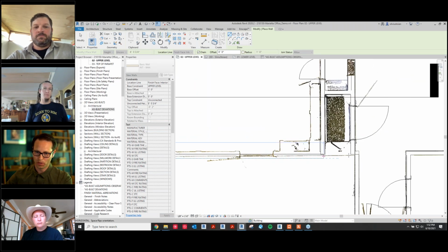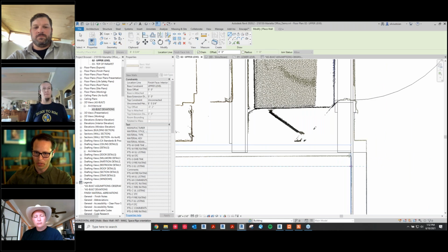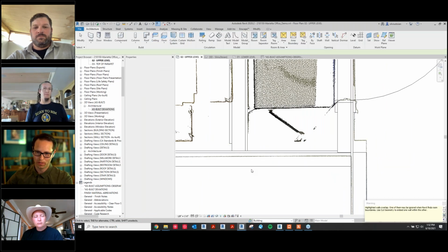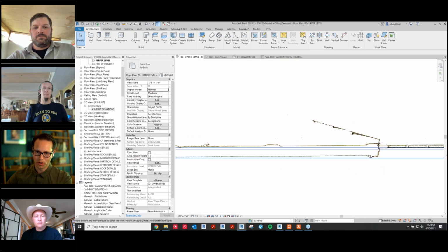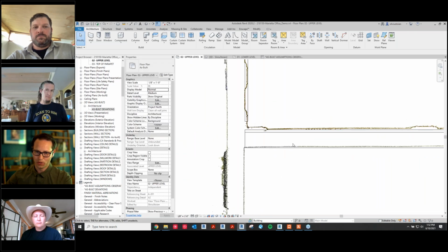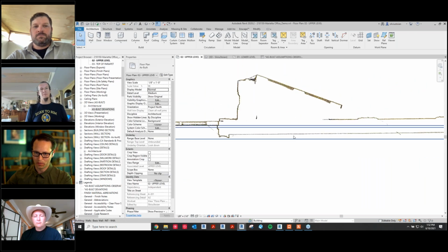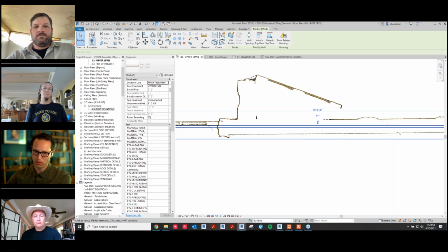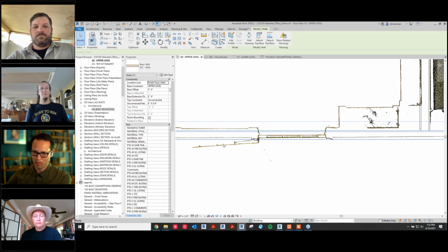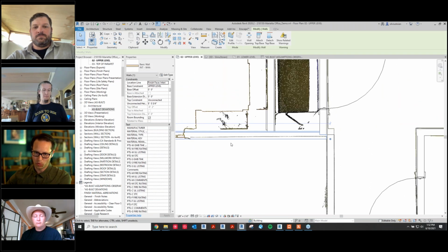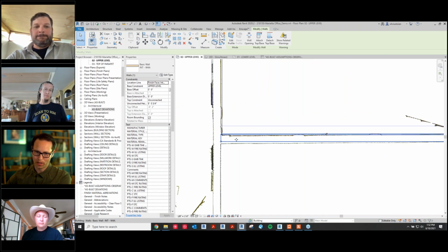So if I pick that corner and I trace it all the way to the end, you see how much off we are here. So you need to find that balance. If you want this wall to be orthogonal, you're just going to push it until you find that balance where you minimize the error at one end and at the other end.